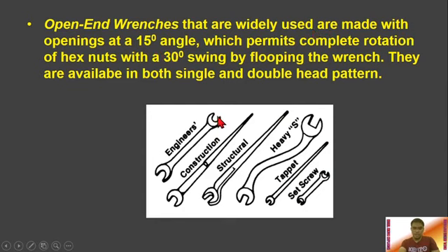So the opening is at a 15-degree angle, which permits complete rotation of nuts with a 30-degree swing by flipping the wrench. So they are available in both single and double head pattern. Okay, so this is the double head pattern. Then we have also the single.